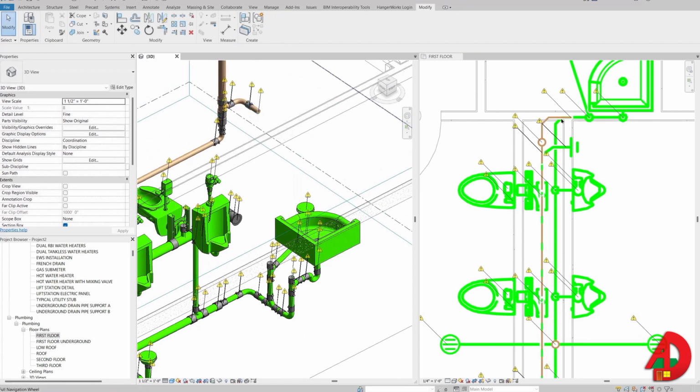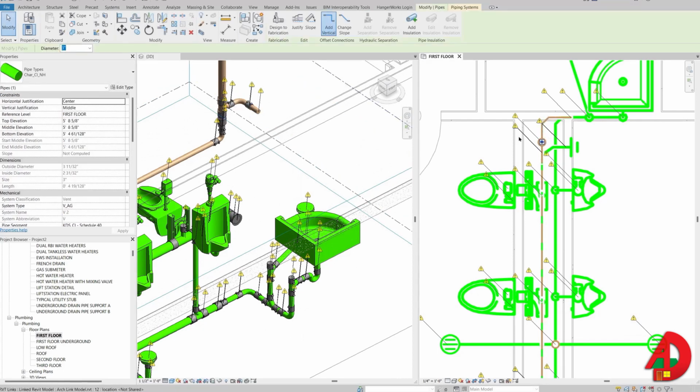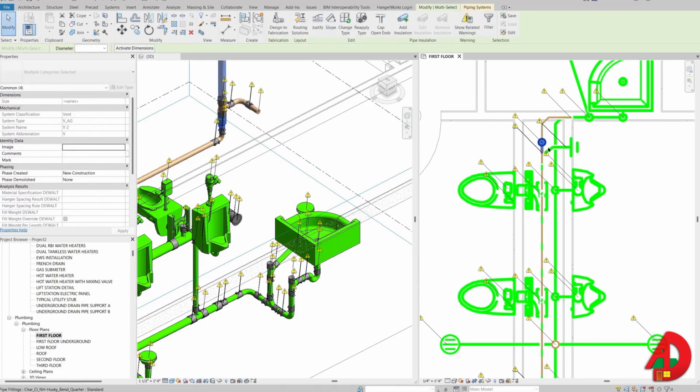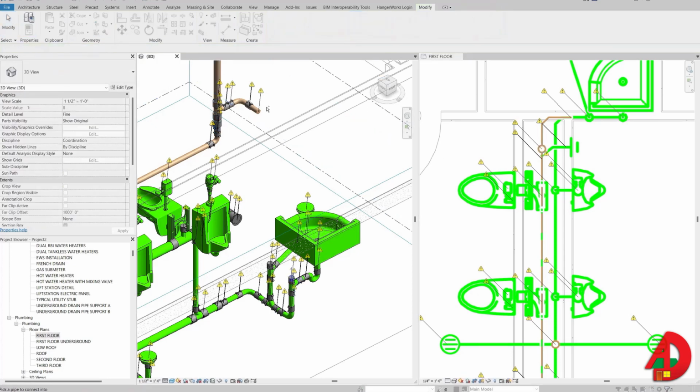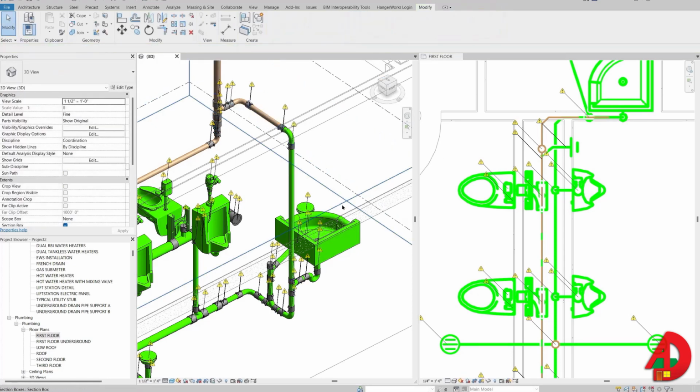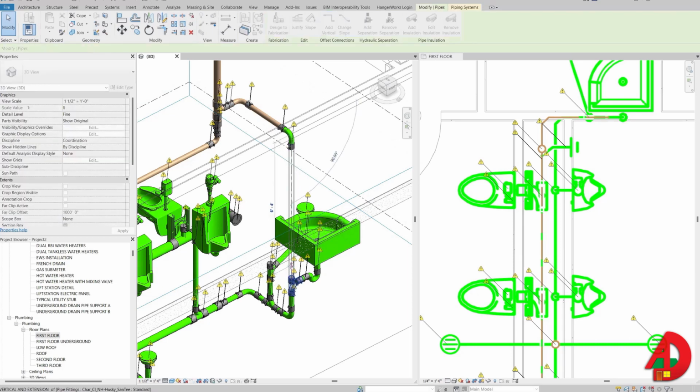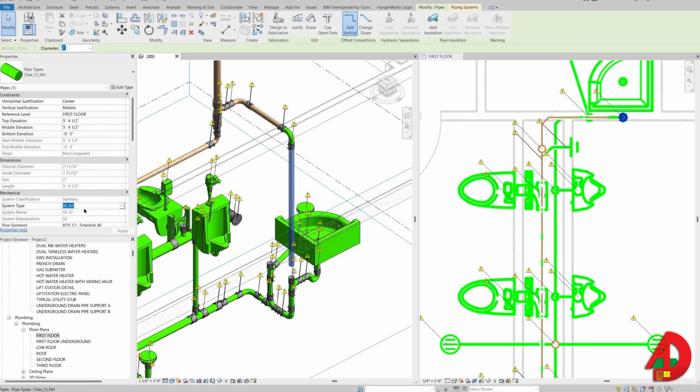Sometimes this will not work because some fittings are too close to each other, and I assume that is the case with the bend and the santee of the riser being too close to each other. And if I try to connect again, it should work. Looks like this vertical segment is green, which means it is sanitary. If I want to change that, I have to drag this segment of the pipe up while holding Shift key,